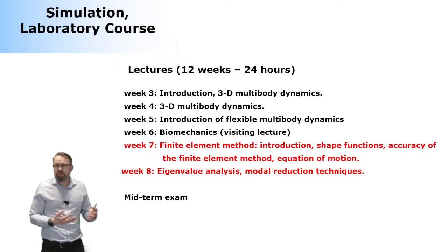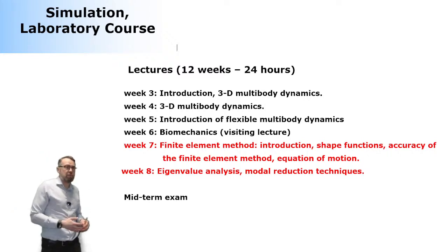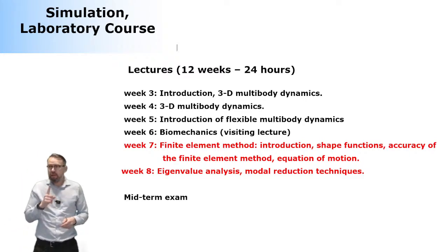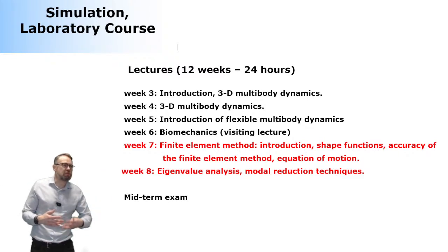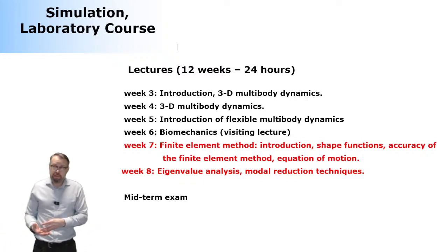The equation based on the finite-element method is almost like the equation based on multi-body system dynamics, with a major difference. And the major difference is this. Typically, the finite-element method is designed for small rotation, so conventional finite-element method cannot handle large rotation. Of course, there are extensions of the finite-element method to take large rotations into account, like the large rotation vector formulation.